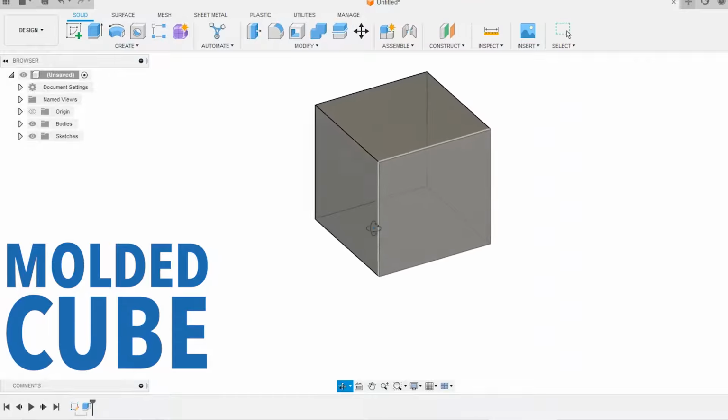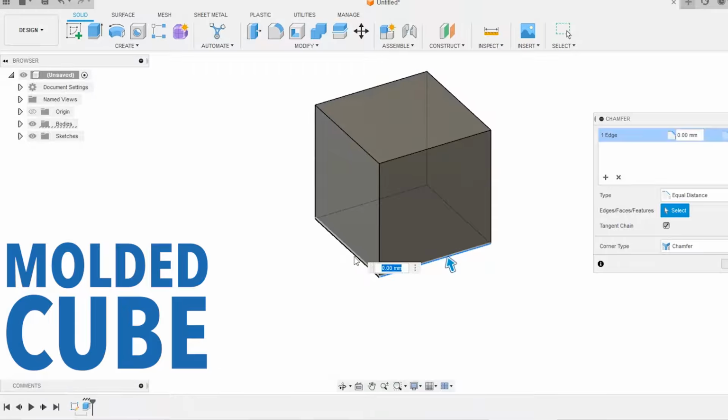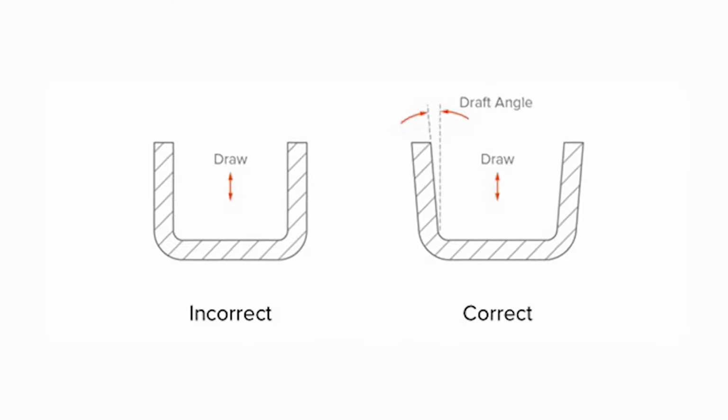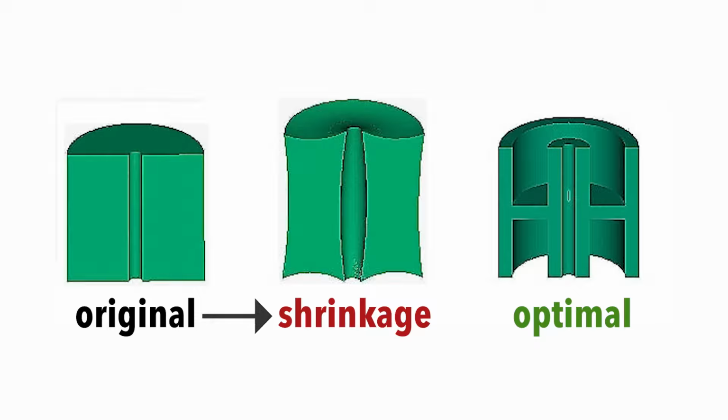And whatever process you decide to use in mass production, you should design towards. But since it's a cube, it's a fairly simple matter to show the two different options. If you are making an injection molded cube, the first thing you have to do is apply a draft angle. You have to apply at least a 1.5 degree angle to the sides of the cube. It's no longer a cube now, but at least it can be removed from the mold.